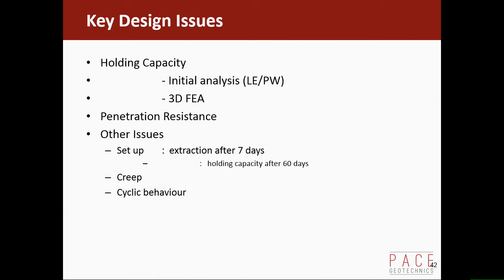Some of the other issues are, you usually allow for extraction after 7 days, so you can put it in and then you can pump water into the pile and push it out. If it hasn't gone in straight for some reason, you can reposition it. You've got 7 days to decide whether you need to do that, whether you can live with it where it is. And the other thing is, at some point it's going to be used, but the soil is reconsolidating, the thixotropy is coming into play. So you've got a time period till it recovers that strength and gains enough strength to actually hold the FPSO in position.